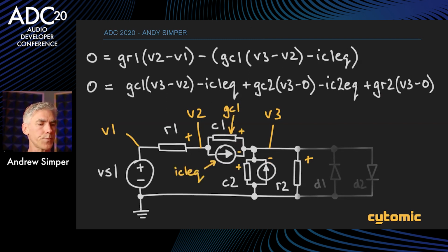We can do that. So in terms of actual circuits, just to let you know, that little y equals mx plus b bit that we turned the capacitor into kind of looks like a little resistor and a little current source. Remember, we're in current land, adding up currents and making them all sum to 0. And that's what it looks like if you drew each little thing as its own little component.